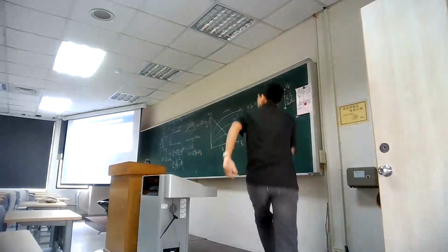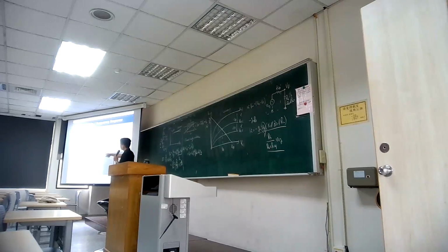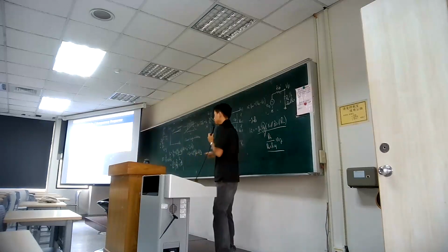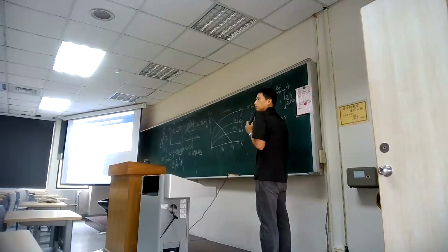Okay, well, the small signal now, right? First, we talked about how much current we can amplify, and then we multiply with the load, and then from the input side, we try to use the voltage divider. So how much signal we can take from the resistance. If you are working with a really high resistance at the gate pole, that would be a good thing for you, because if you look at this function, if you want to pass your signal well into VGS, you need to make sure RG should be really large, right?